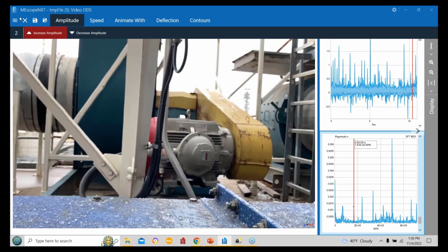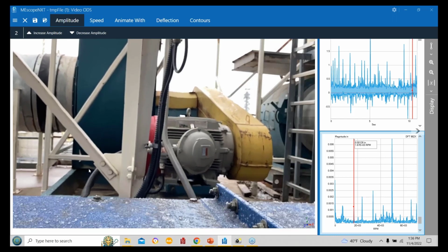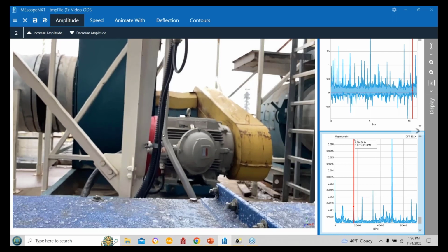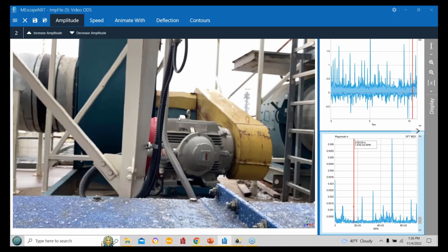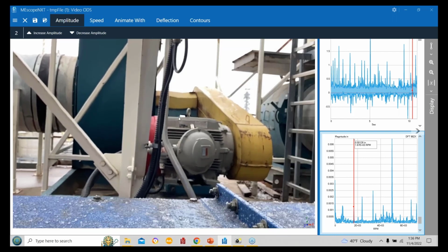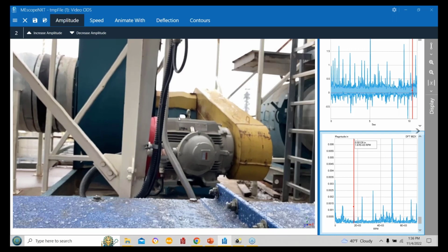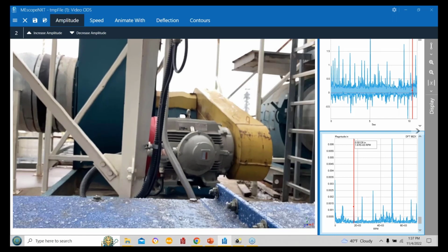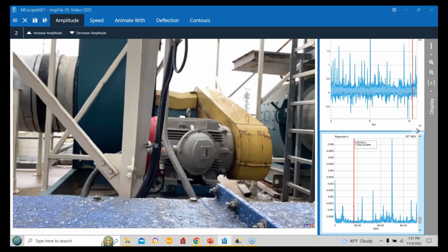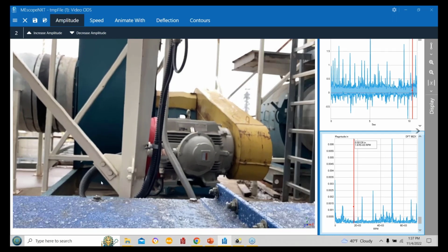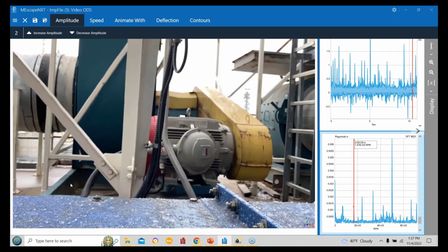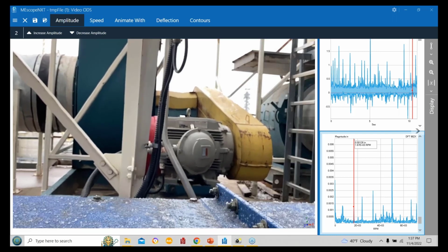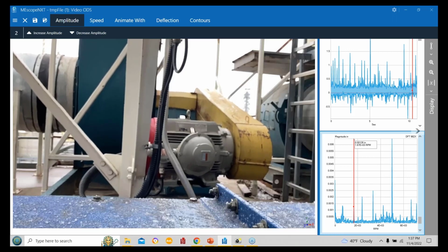Little story about this. This green frame under here goes all the way to the other side. Obviously, the fan sits on it, the motor sits on it. It sits on isolators. This is on the roof of a, I can't tell you what it is. It's a processing plant. There are 4 isolators on this thing, which was probably not enough. They only replaced the front ones up here. The back ones they let go, and so some were bottomed out and some weren't. I don't know why, if they didn't have enough isolators or what.